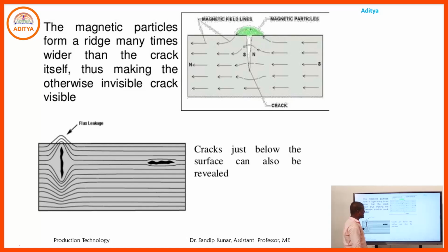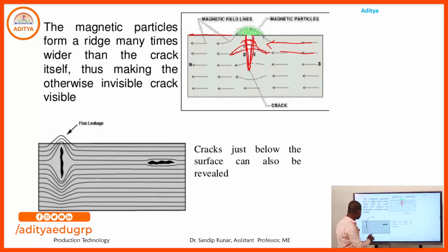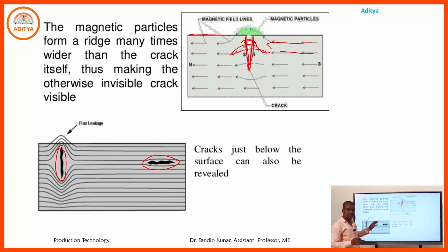Here, as an example, a crack has formed in the weld joint. When the magnetic lines go from the south side to the north side, due to the presence of the crack, the magnetic lines will be deflected. We can easily see on the digital device that they are deflected. When they are deflected, we decide that welding defects are present in that place. So based on that, we take care of those welding defects.